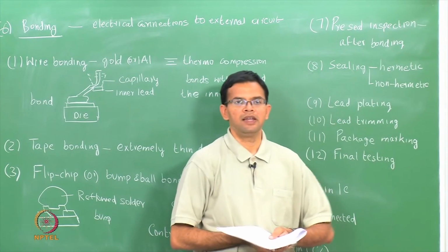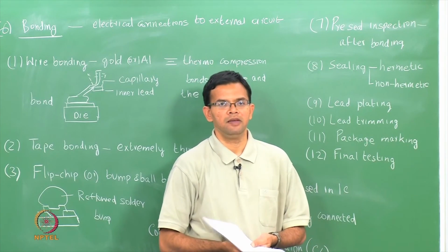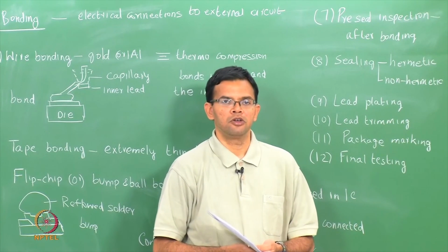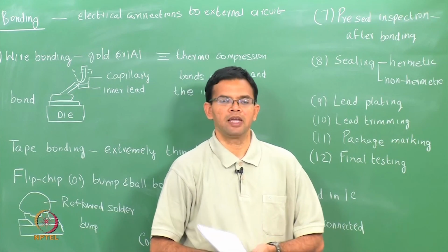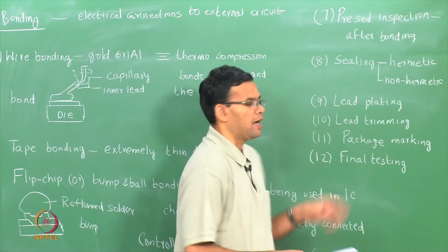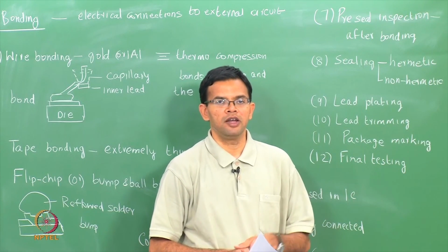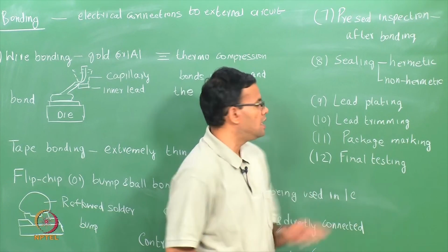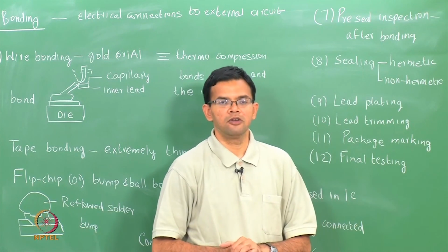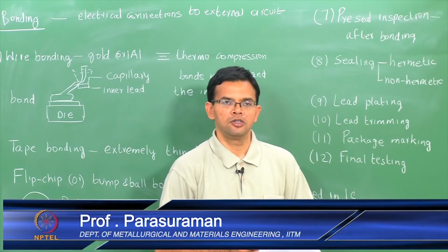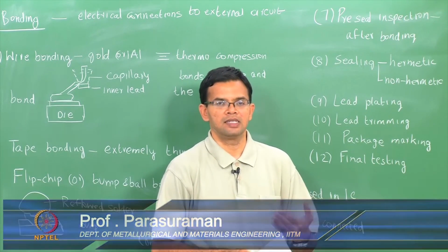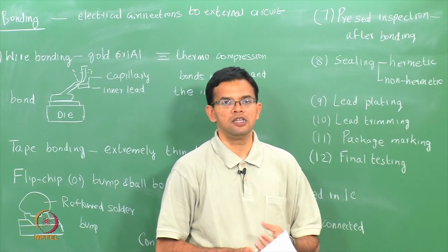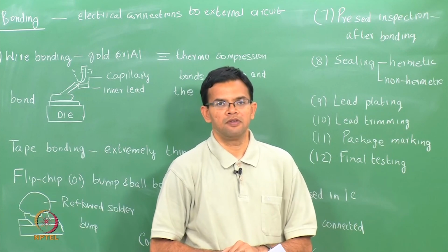At the end of the final testing, the package is ready and it can then be integrated onto your system. It could be a part of a system on a package deal, or it could be a package where all the components are already integrated into it and then it becomes a system on chip. So, these are the various steps that go into the packaging process. Once again you can think about it as an assembly line where the final dies go through these series of steps in order to give the final package.